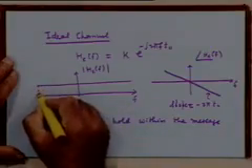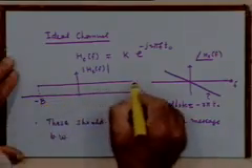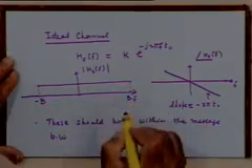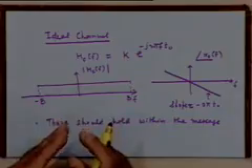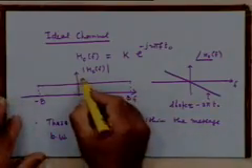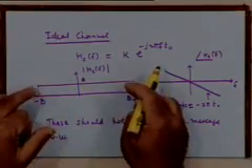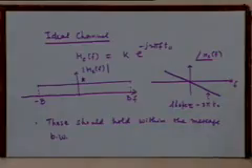So let us say if the message bandwidth is b, we would like the transfer function magnitude to be constant, equal to k, between minus b and plus b. Whether it is constant beyond that is not of any interest to us, right?